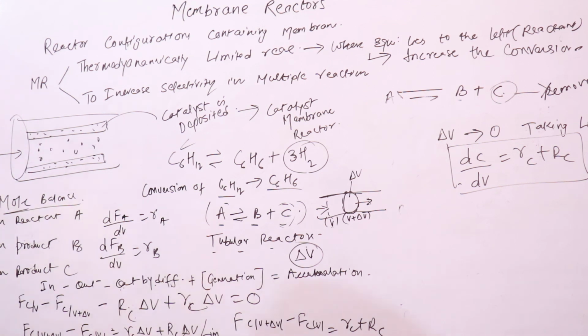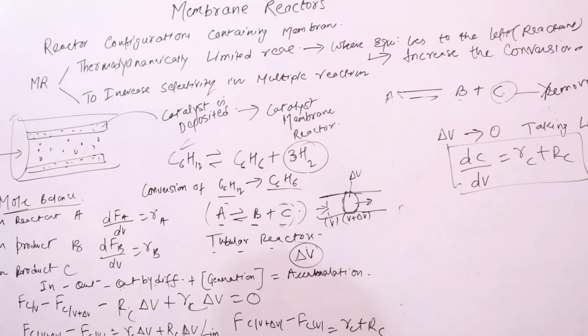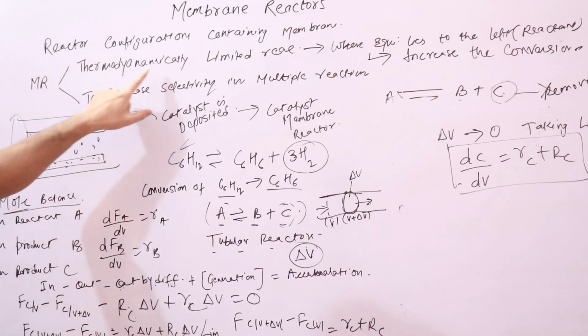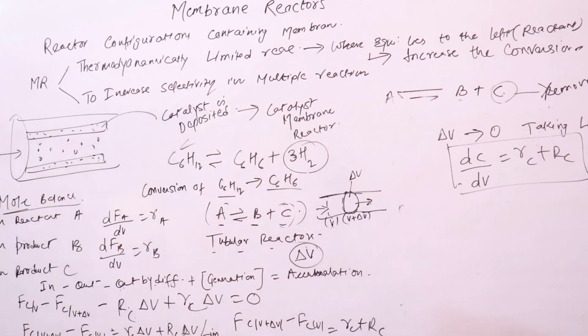Just remember mole balance, and you can check the tubular reactor lecture if you don't understand mole balance or have any doubts on it. In membrane reactors, just remember, membrane reactors are used for thermodynamically limited reactions to increase the selectivity in multiple reactions.